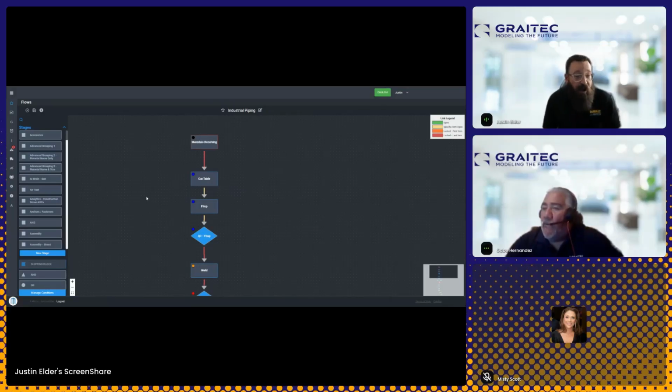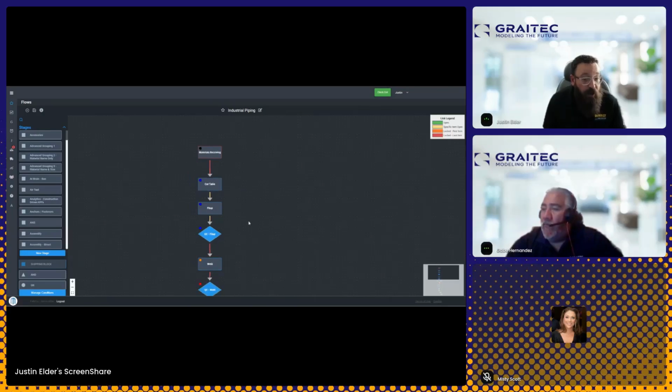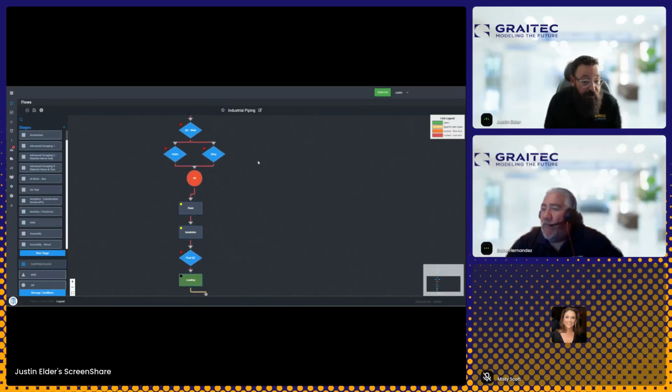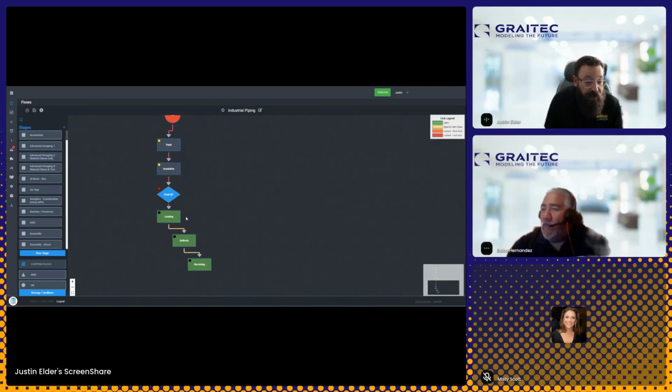So as I saw on that last one that was 88% done, I have done all the materials receiving for that drawing. I've done all the cut for that particular drawing, and now it is in fit up. And so we can see through the line how that's going to eventually work its way into completion, into a loading stage, delivery, receiving, which is install.